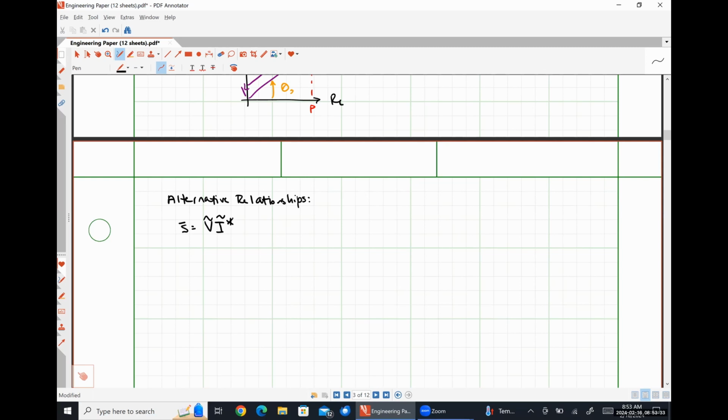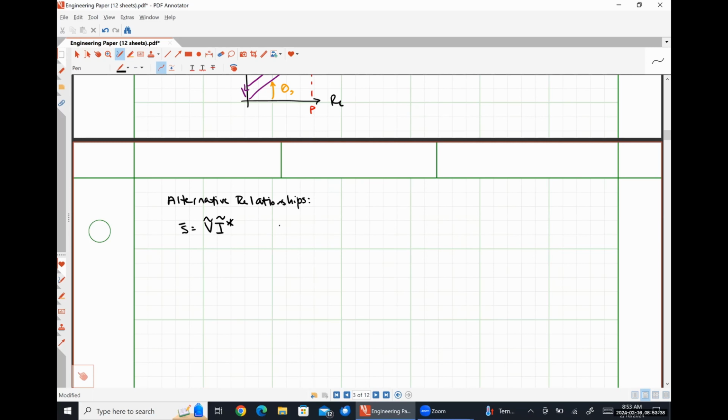First, my fundamental definition for complex power. And then this one over here, V is equal to I times Z. What is that second equation? Ohm's law, that's it. Going back to very, very basic things here. So I can use these two equations together to express the complex power absorbed by anything only in terms of the voltage or only in terms of the current.